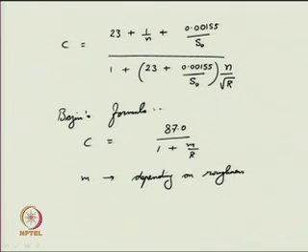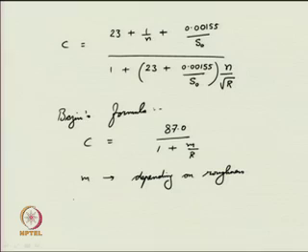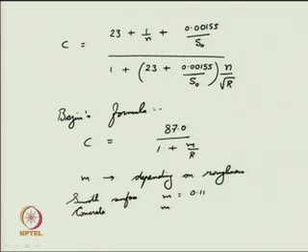In fact, there are some tables to identify m using Bazin's formula. What are the m values? For example, for smooth surface, m is equal to 0.11. For concrete, m is equal to 0.21. For earth channels, you have values ranging from 1.5 to 3.1. You can just note it down.